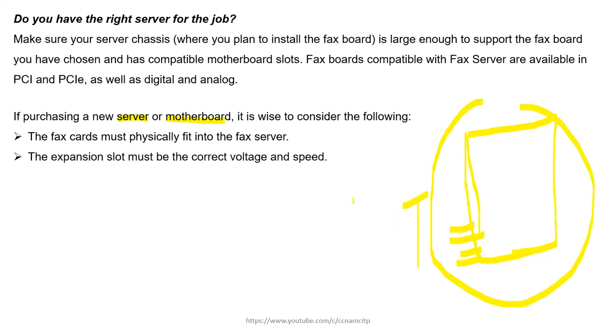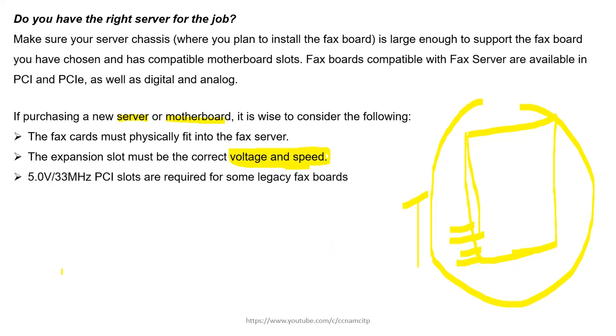And the next one, the expansion slot must be the correct voltage and speed. Yes, you have to worry about that. You need to know what is the voltage of that expansion slot, and the speed. The next thing, check if it is possible: 5.0 volt and 33 megahertz PCI slots are required for some legacy fax boards. So go with the specification of the server, motherboard, and PCI slots, as well as the specification of the boards you are purchasing.